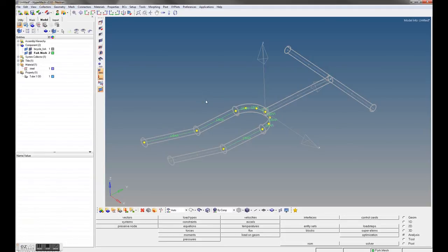All right. The last thing I'm going to do here is just export the BDF file. Now, I'm going to do that at this point because you can actually create the mesh in Hypermesh, export the BDF file. And if you want to add in all the forces and the SPCs and the load steps by hand, directly on the BDF, that BDF file that gets exported, you can do that, okay? So I'll just export it here. Or you can make the whole model in Hypermesh and export that final BDF and run that in Nastran. Either way is fine.